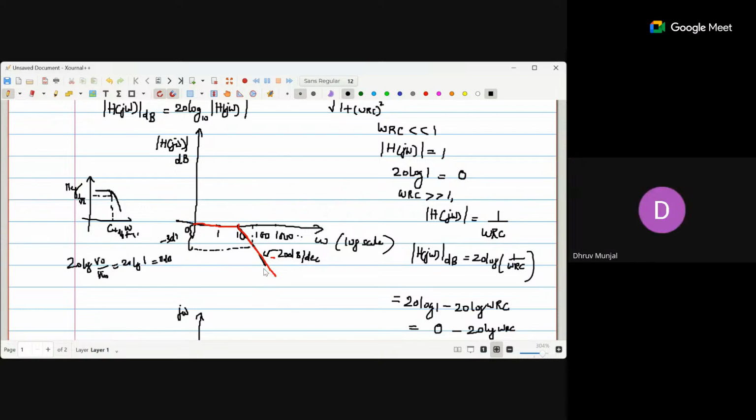So, ma'am, if I am getting 0 dB, that means I am getting no signal at the output? 0 dB refers to the range of frequencies for which your output amplitude is the same as that of the input. That means the frequencies that the low pass filter passes. 0 means there is no change. You are confusing the ordinary plot with this dB plot. What you did last time is the same as what we described here, but the difference is in the scale.